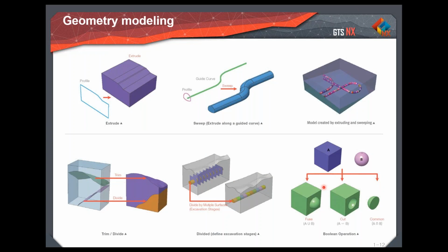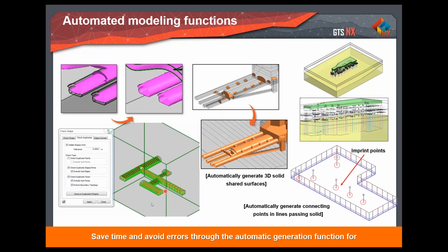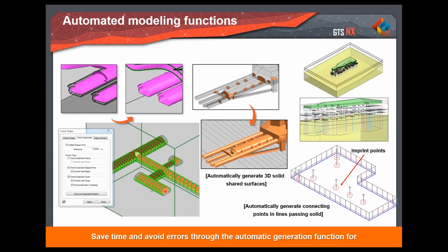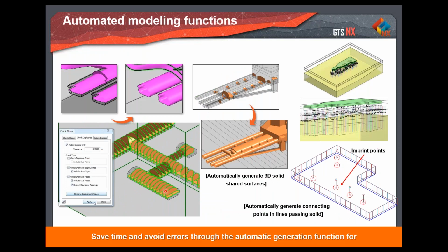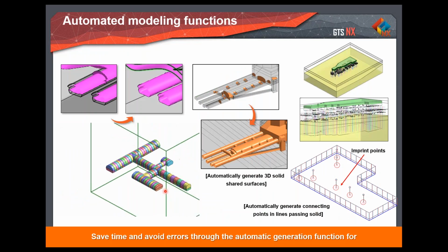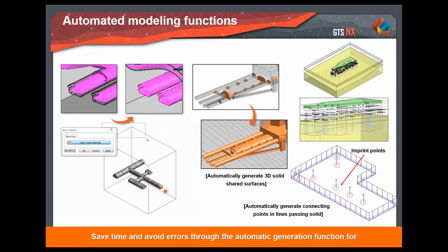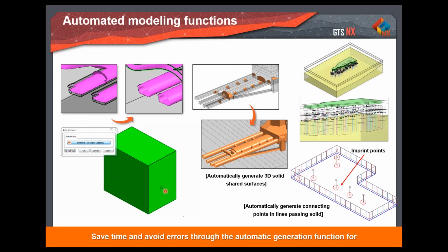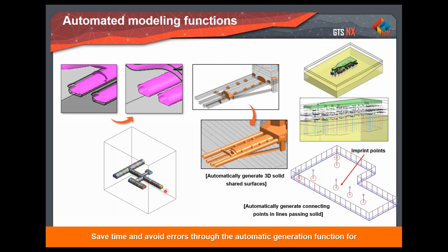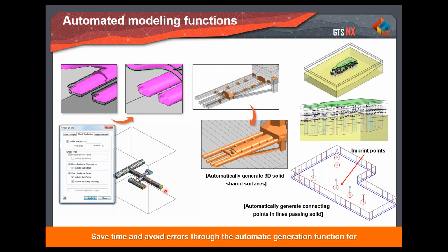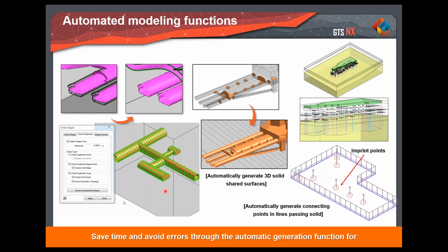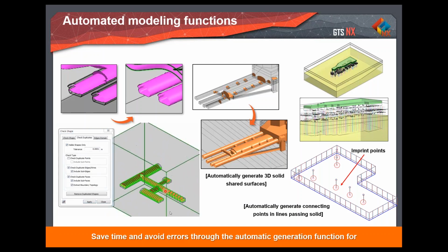Basically, in order to find a good contact between one solid and another, there will be a number of layers present in the geotechnical model, and there will be a number of solid parts. So one part should be in contact with the other part in order to have a complete stress transfer or complete nodal connectivity. Basically, it should have nodal connectivity so that the stress would get transferred. So in order to have nodal connectivity, it is very important to use the Boolean operation.